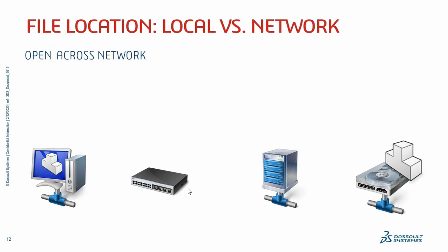So you have to check whether you want to go for the network. If you find the assembly is lagging and very slow, you have to grab the data which is on the shared network onto your local PC, then open it and perform the assembly functions. So file location really matters. Keep in mind that a file location on your local PC takes less time than the network.